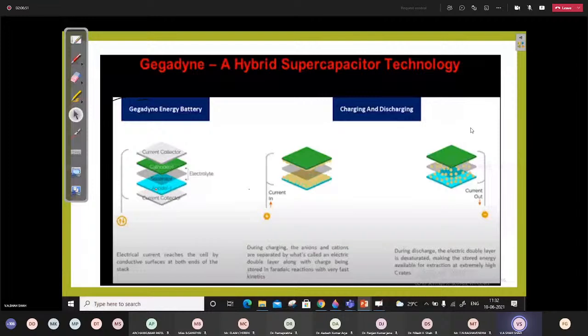This is one of the simulations, with the equivalent representation of the battery with its voltage and resistance, and the supercapacitor capacitance value and its ESR. I have taken this example with a battery voltage of 16 volts and an ultracapacitor voltage again of 16 volts, and they are charged with a pulse load of different duty cycle. You can see here this is the pulse load, this is the high power and this is the low power in which your current distributions will take place.